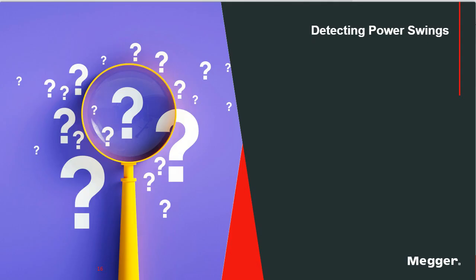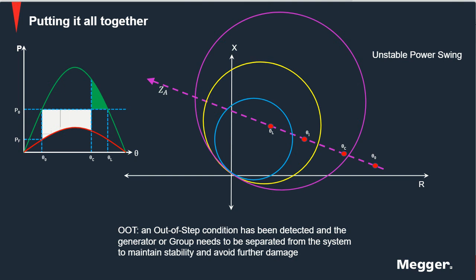If we had a fault, and we had, for example, this condition of operation here, and there is a fault, the relay trips. The impedance in the system moves almost immediately to the impedance of the fault. So the movement from this point where the system was operating, the load point, to the fault point happens very quickly when you have a fault.